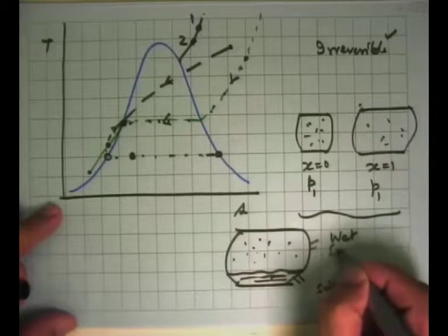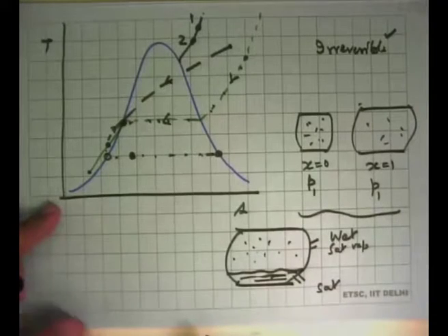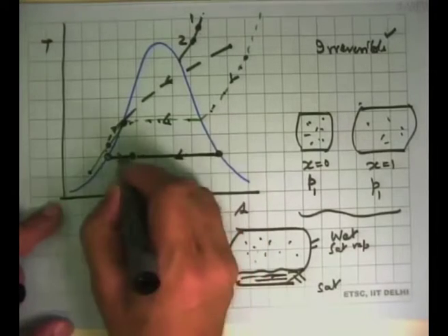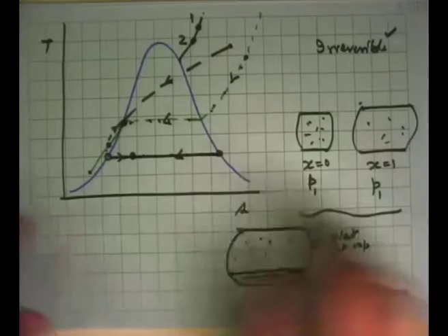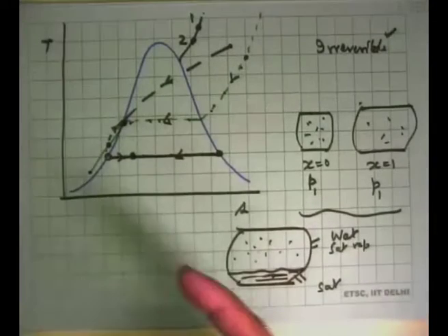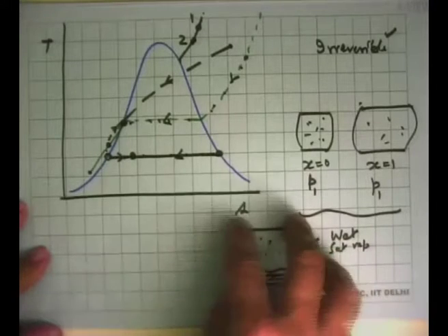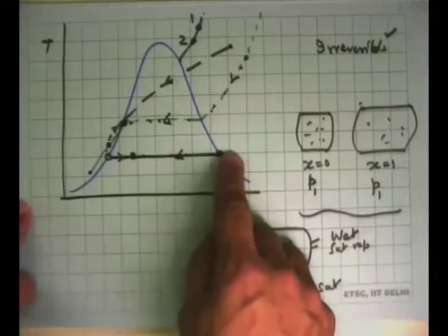Take this out, we get our saturated vapor, and so we got back our initial states. In some sense, this mixing of saturated states is a reversible process. It doesn't produce a new state in the sense that pressure and temperature are different, but we just produce a mixture where the proportion of saturated liquid and saturated vapor are different.